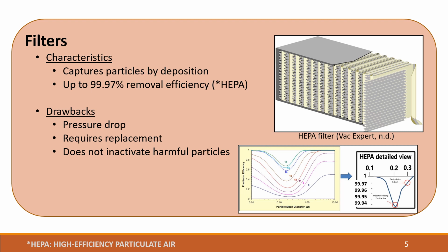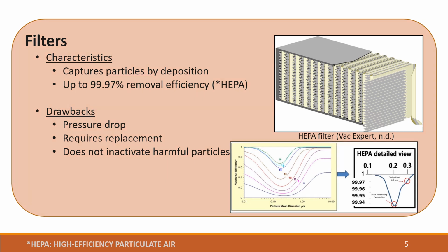However, there are a few drawbacks. If you can imagine, the better the filter is, the less it lets through, and that generally also includes air. So there's usually a pressure drop associated with a given rating of filter. Also, filters require replacement over time, and perhaps most importantly, they do not inactivate the harmful particles that they capture.